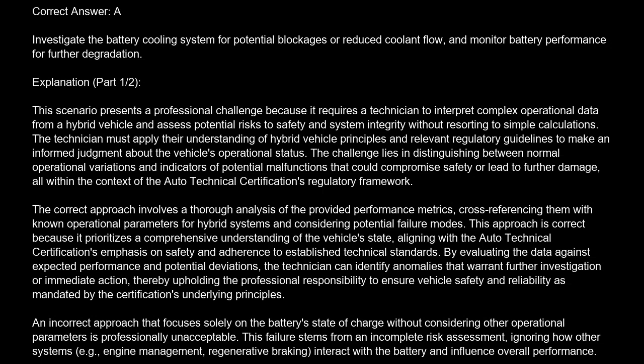The correct answer is A. Investigate the battery cooling system for potential blockages or reduced coolant flow, and monitor battery performance for further degradation. Explanation. This scenario presents a professional challenge because it requires a technician to interpret complex operational data from a hybrid vehicle and assess potential risks to safety and system integrity without resorting to simple calculations.